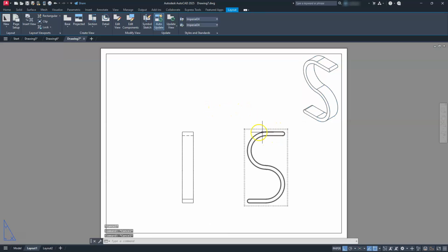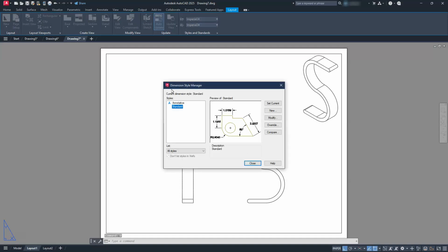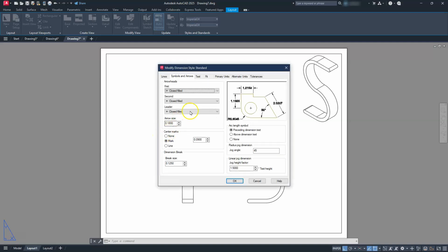All right. Now let's go ahead and put some quick dimensions on this thing. The way we're going to do that, I'm just going to go to D, enter. Remember, you always have to set up your dimension style first. We're in paper space, so 1:1 is perfectly fine. So therefore, it doesn't matter which one of these you use. I'm going to go to modify. And I always start from the right to the left. You know, kind of way my backwards brain works here.